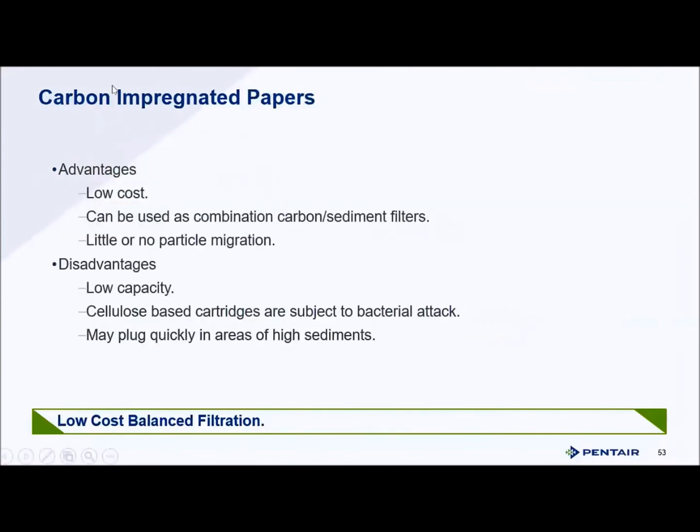Advantages of carbon impregnated paper filters: low cost. They can be used as combination carbon and sediment filters, but they're low cost. They're going to plug relatively quickly and have short lives. Little or no particle migration. Disadvantage is low capacity. Cellulose-based cartridges are subject to bacterial attack and may plug quickly in areas of high sediments. This is your low cost filter to throw in for free, essentially.